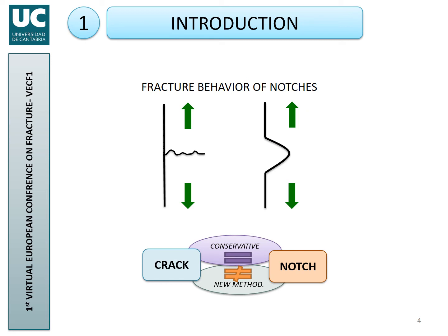This is what I was mentioning before. Cracks and notches are different. Notches do not have a zero radius on the tip, and then the stress fields are different, and we should develop specific methodologies addressing this particular situation. Because if not, if we treat notches as cracks, this would be a really conservative practice.